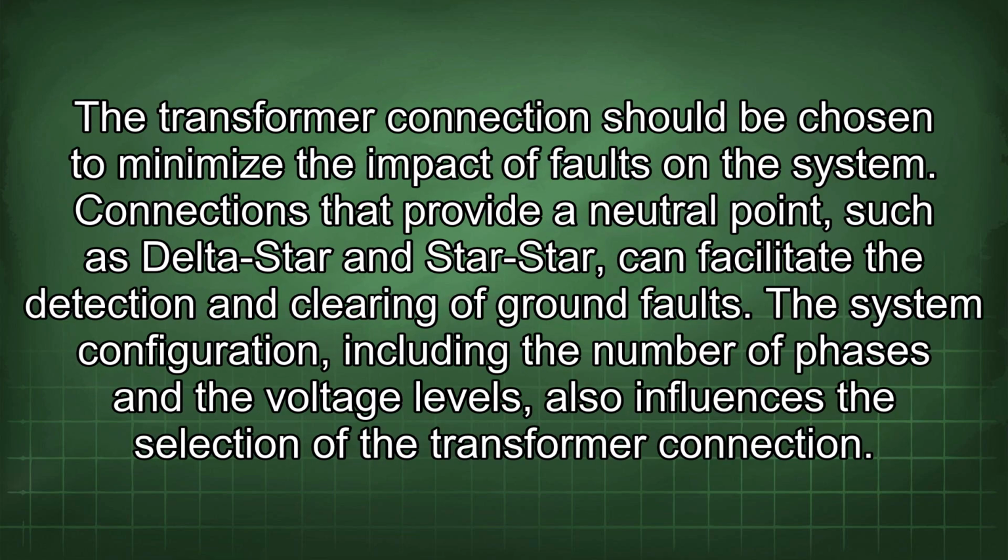Moreover, fault conditions and the need for system protection are paramount. The transformer connection should be chosen to minimize the impact of faults on the system. Connections that provide a neutral point, such as delta star and star star, can facilitate the detection and clearing of ground faults.